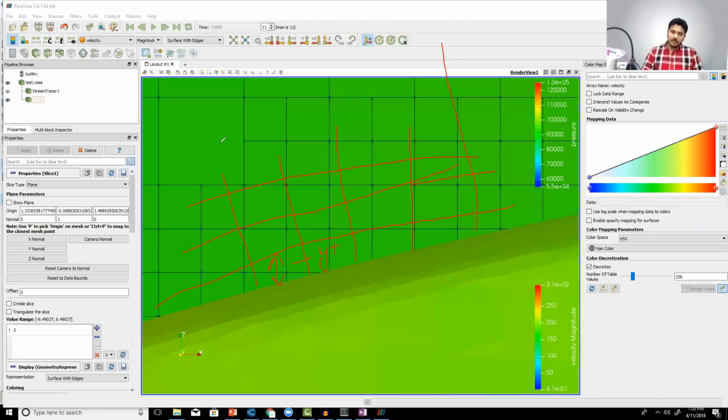What people do in aerodynamic simulations is near the wall, the mesh is very refined, and as you move away from the wall, the mesh becomes bigger. There is a particular expansion ratio, which is called E. This expansion ratio is very important. You need to check that as well. Rishikesh, I hope that answers your question.